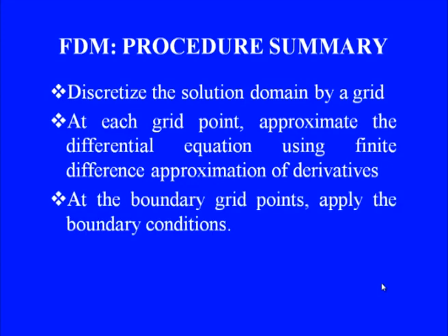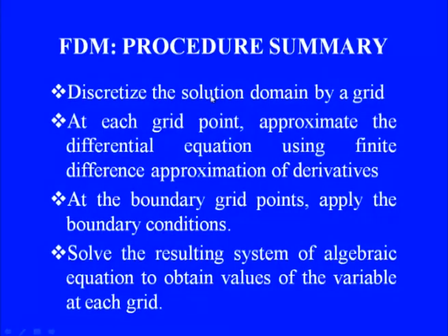Then once we have generated the equations at all the interior points, we need to come to the boundary points and apply the boundary conditions, wherein we have to modify the matrix coefficients for boundary nodes taking care of the specified boundary condition. And then once we have done that and we have got our algebraic system of equations, solve the system of equations. So basically this step by step procedure tells us a modular decomposition of our code, like each step which we have outlined here could be made a separate function, a routine or module, whichever term you prefer.